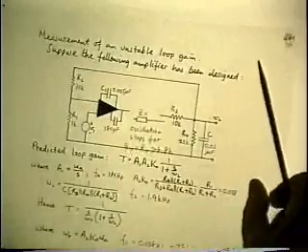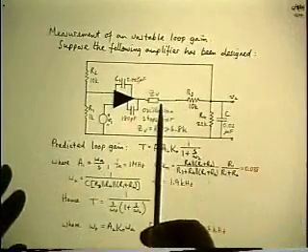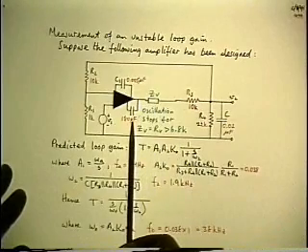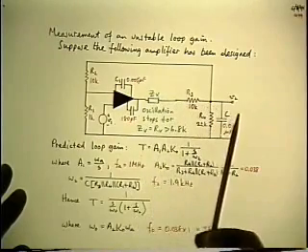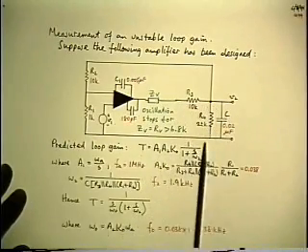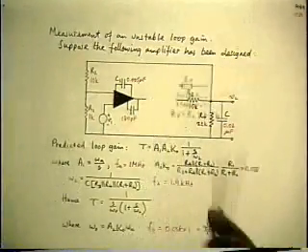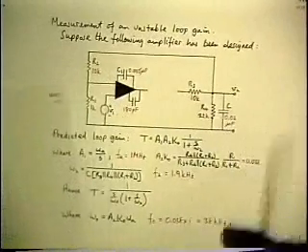This is what you do when you stop it oscillating. When you put that impedance in there, the actual loop gain is, of course, changing, because you're making the divider ratio out here smaller and smaller. So the loop gain is falling. And in fact, in the limit, if you made that impedance infinite, you've opened the loop. And it better stop oscillating.